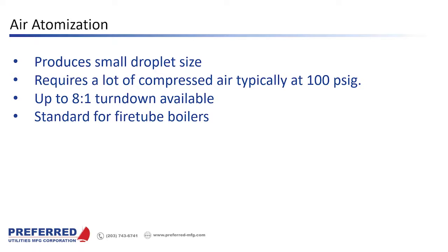And water tube boilers in the old days were lit off by hand. Nowadays, it's more often to light them off automatically. But in the old days, you would sit right in front of the burner, and when the burner goes to purge, you would open up the steam line, dump all that water into the boiler, and then continue to run steam through that line to get the line hot and to dry out the line and dry out your steam.